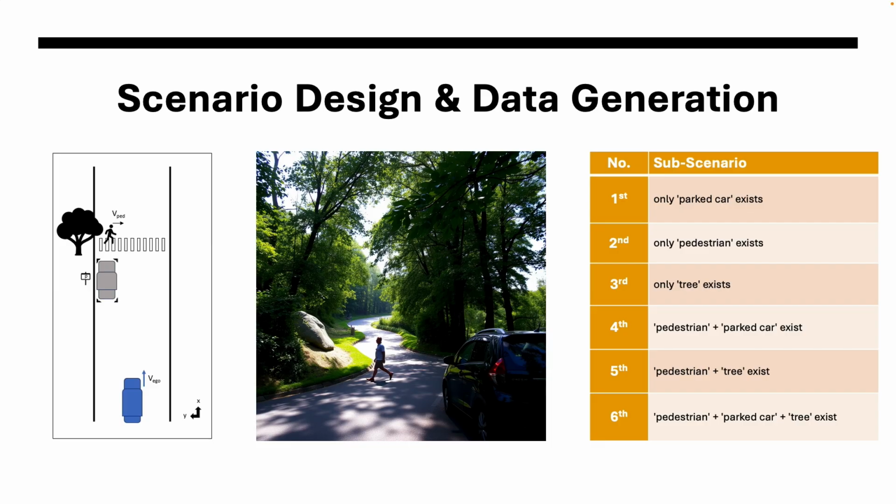In our scenario, we simulate an ego vehicle navigating a typical urban road, and it is equipped with an FMCW radar working at 77 GHz. Alongside, there is a car parked on the side of the road, a pedestrian randomly walking toward the road, and a tree with branches swaying in the wind to represent the vegetation. The purpose here is to evaluate if a CNN can detect and classify the pedestrian correctly, even when the radar signals are cluttered by dynamic elements like moving tree branches.